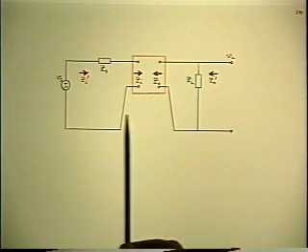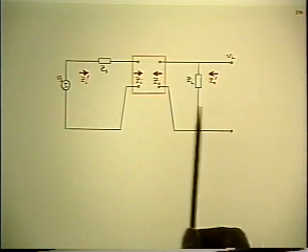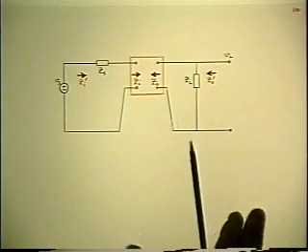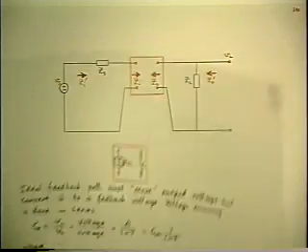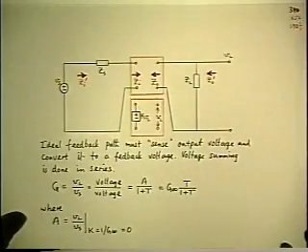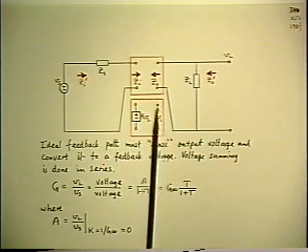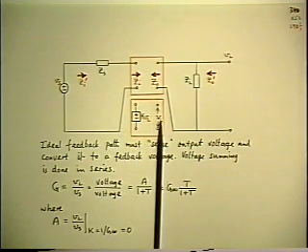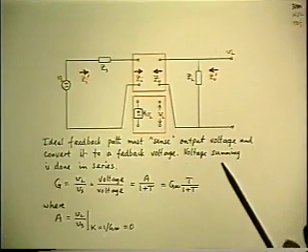Let's suppose we want to apply feedback in the way that's going to make this non-ideal amplifier approach more closely the ideal voltage-to-voltage amplifier. That is, we want to raise its input impedance and we want to lower its output impedance. How are we going to connect the feedback path? So here's a feedback box, and I'm idealizing it. Now, how are we going to connect it?